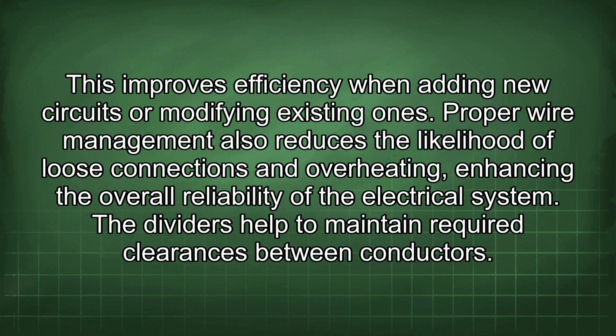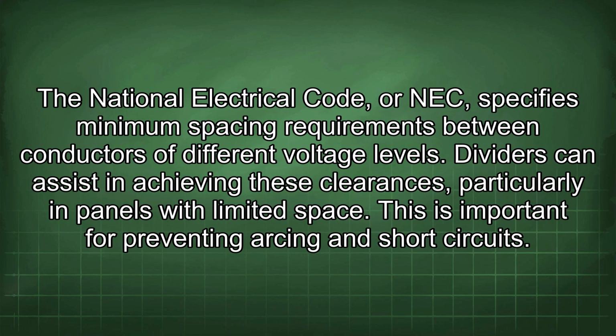The dividers help to maintain required clearances between conductors. The National Electrical Code, or NEC, specifies minimum spacing requirements between conductors of different voltage levels. Dividers can assist in achieving these clearances, particularly in panels with limited space. This is important for preventing arcing and short circuits.